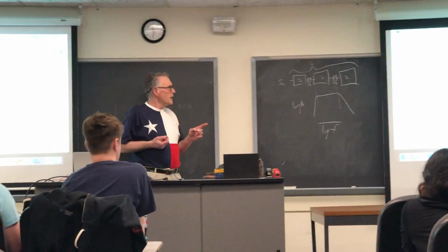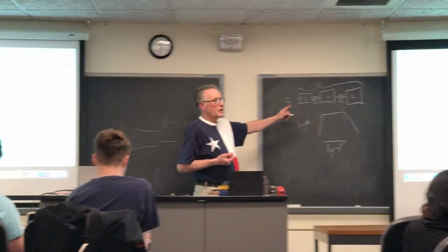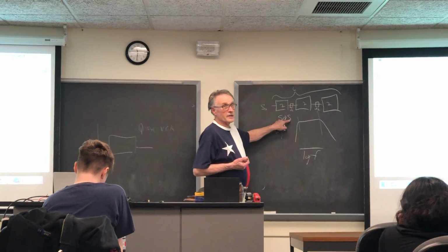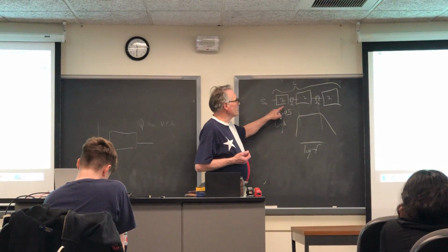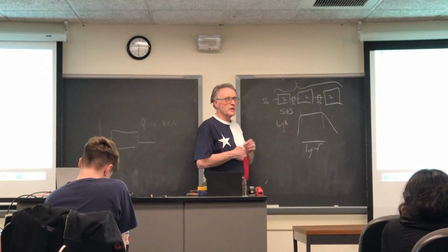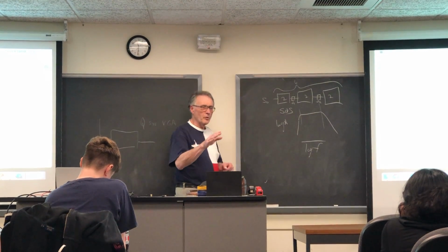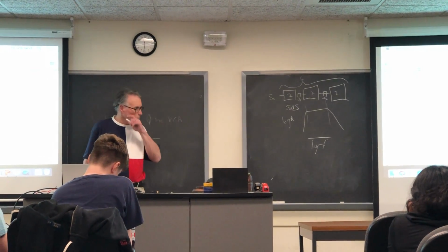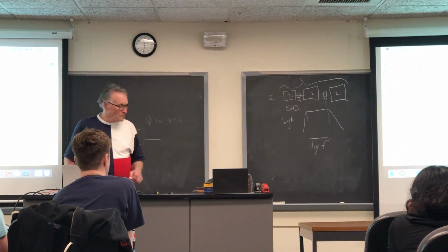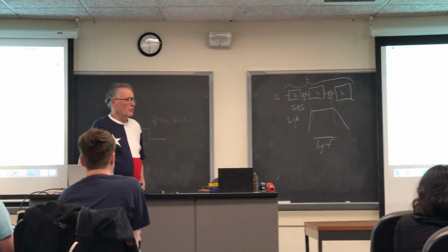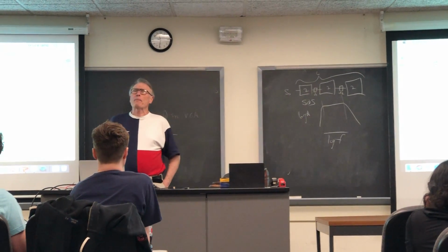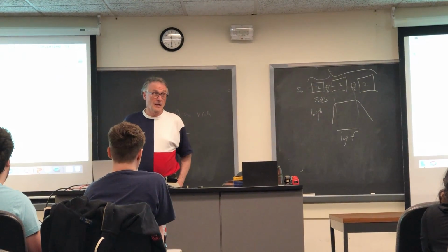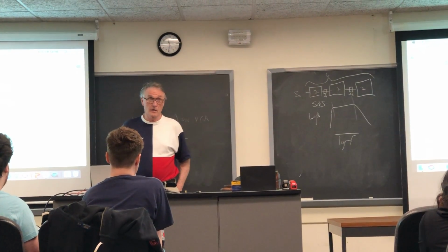So a high order filter that's been written as second order sections is easier to write in floating point than in fixed point. And I built some of those at one point using a 9-bit mantissa, and they worked just fine.